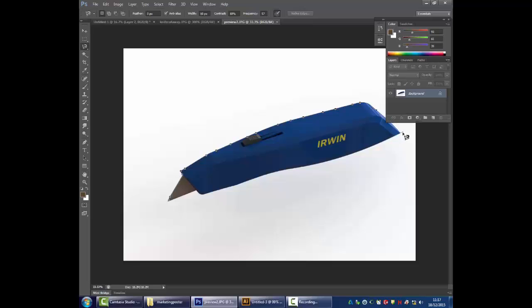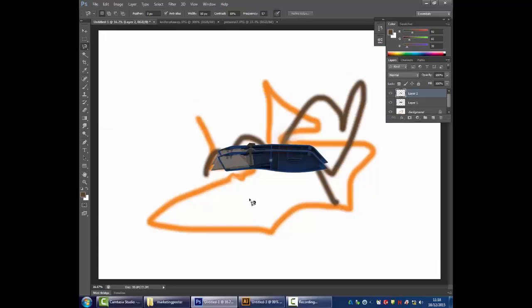Can you see I might deviate off it a bit, and it thinks, yeah, I want it to have that space. But generally, where you've got an image where it's pretty obvious where the outline is, this works quite well. And then if you hit enter just to finish, it'll finish it for you. So Control C to copy that over, Control V, paste that over like that.